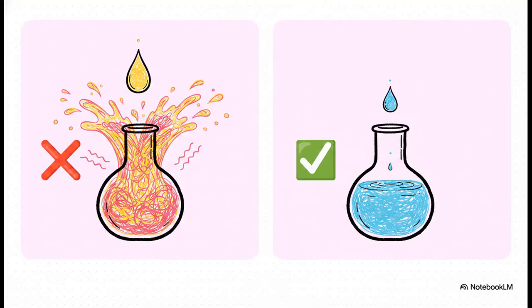Handling the chemical itself requires very specific techniques. If you ever need to mix or dilute this stuff, there is an absolute unbreakable rule. Slowly add the KOH to cold water. Never, ever add water to the KOH. Because of that reactivity rating we talked about earlier, adding water directly to the caustic liquid generates explosive heat, which can actually cause the chemical to violently boil and splash right back onto you. Always add KOH to water. Do it slowly, and preferably use cold water to manage the temperature spike.